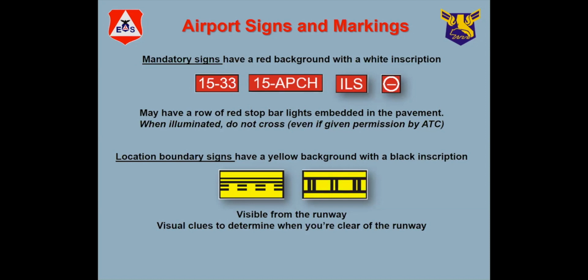Is that the right terminology, Colonel? Yeah, sometimes if you have a taxiway going right across the end of a runway, there'll be a sign like that to warn you that even though you won't be on the runway, you'll be affecting the approach to that runway. You're approaching it. ATC clearance across that. So it's a runway 15 is coming up, be aware.